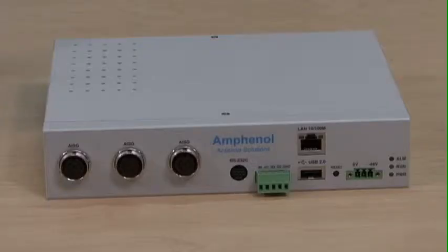Site Control Unit, or SCU. The SCU is a site controller for AISG devices installed at a cell site. It's compatible with the AISG standard and can control up to 24 AISG 1.1 and 2.0 devices such as RETs and TMAs. It provides a web interface performing antenna tilt adjustment, TMA mode adjustment, and device monitoring from remote locations.